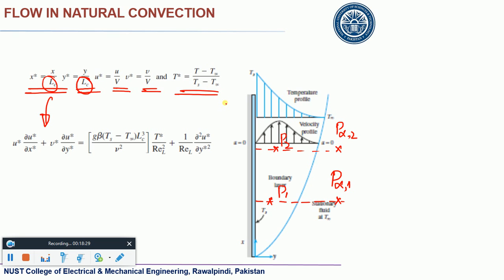It is not that straightforward to write down the characteristic length as equal to the length or diameter of the body. I would show you a few relationships, and those characteristic lengths are again part of the correlations. Once you use these parameters for non-dimensionalization, this is what you get out of it.